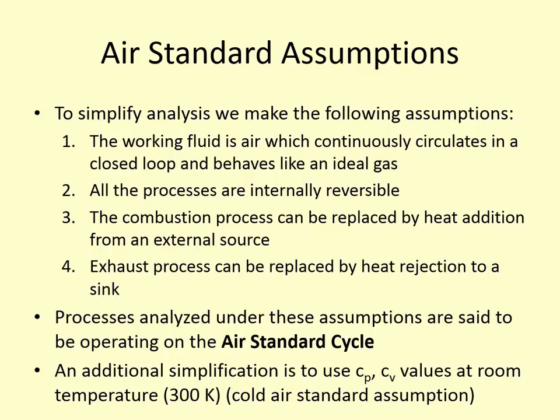All the processes are internally reversible, so we've eliminated friction. We're assuming it's quasi-equilibrium. We're not worried about heat transfer to the surroundings. And then with the combustion process and the exhaust process, rather than needing to know some specific mass balance and stoichiometric ratios to determine what's coming in, what's coming out, we just say, okay, instead of worrying about the mass that's coming in, we're just going to assume that we're replacing these processes with a heat sink and a heat source.